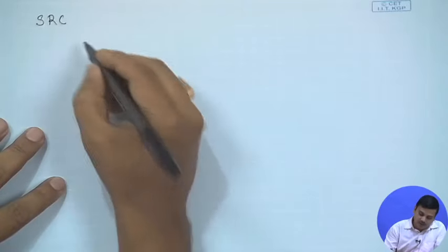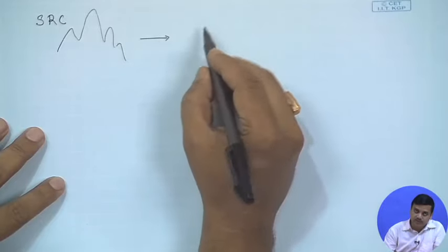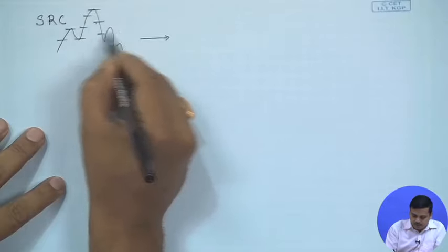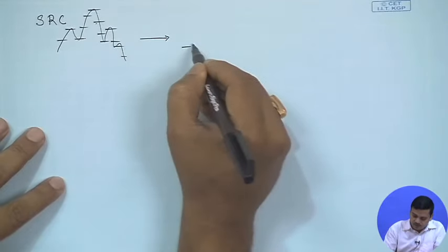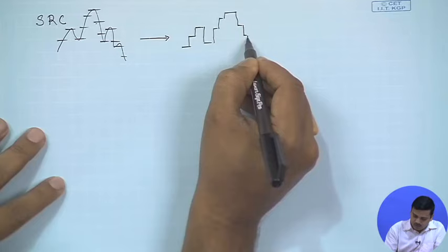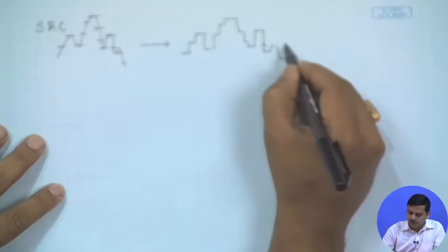So effectively, if we were to summarize, we are going to use almost the entire knowledge of analog communications to establish a digital communication system. In the previous lecture we said, suppose the input source is an analog source, that means if we have this analog waveform, you would first have to convert it into discrete, let us say you quantize it into these levels, and once you quantize it into these levels, your waveform might look like this, and so on, and this one you pass on to a carrier.